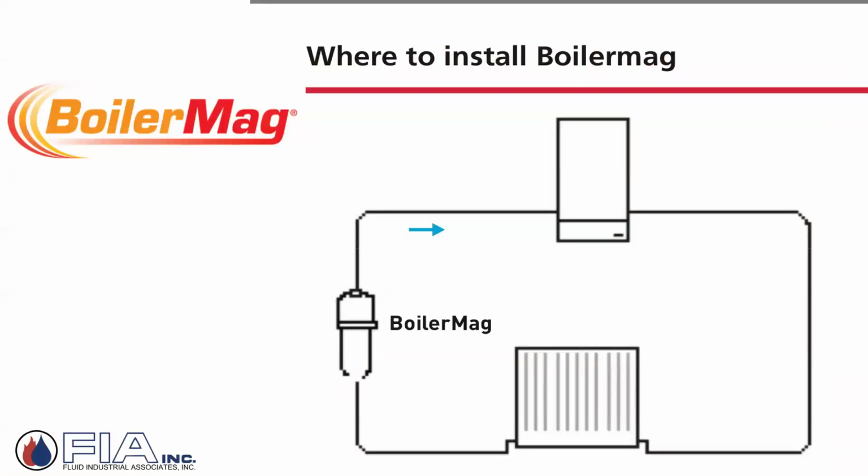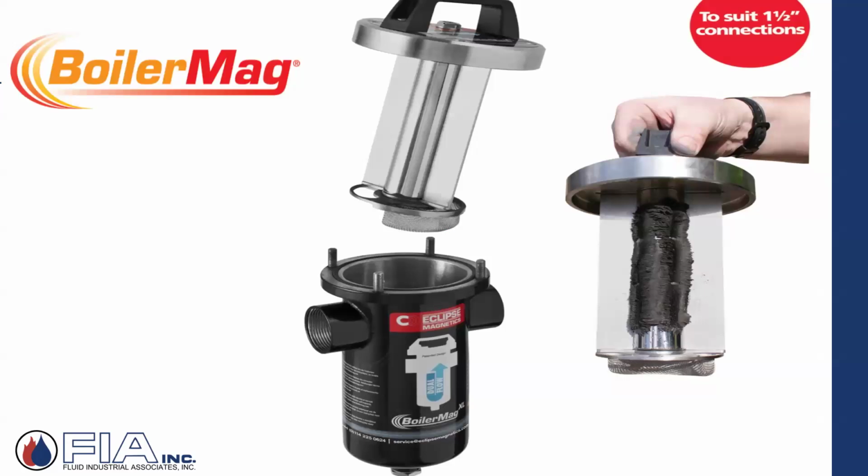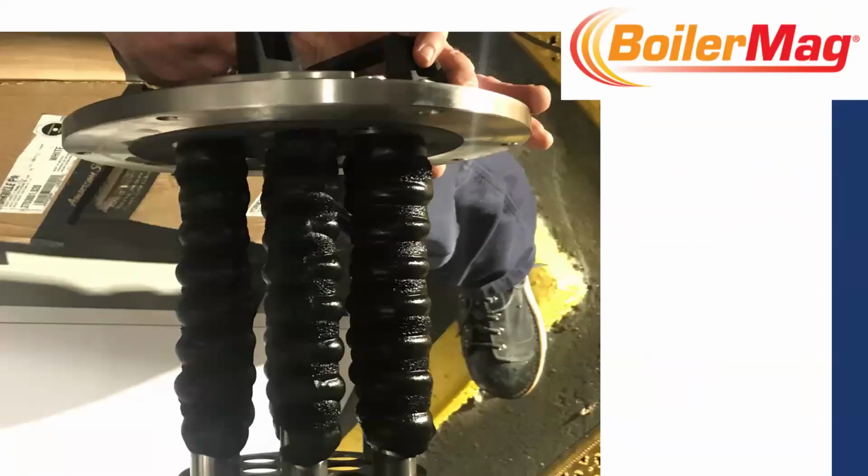Let me just show a quick example. Typically it goes on the return coming back, before you get to your boiler and your boiler pumps and your distribution pumps, which would be over here. And again, there are different sizes. The point of it all is these iron oxides will just get attracted to that. And it's amazing, that picture there is going into an existing building, and like a week later they come back and inspect. So pretty aggressive.